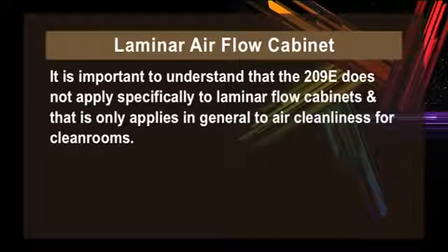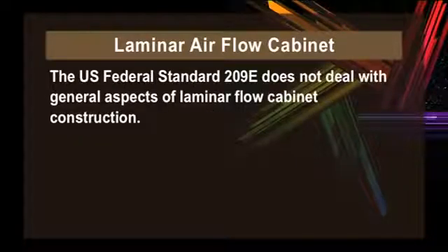It is important to understand that the 209E does not apply specifically to laminar airflow cabinets, and that it only applies in general to air cleanliness for clean rooms. The US Federal Standard 209E does not deal with general aspects of laminar airflow cabinet construction. However, it deals with the most important aspect of cabinet performance, which is the level of product protection provided. In other words, the cleanliness of the air within the working area of the laminar airflow cabinet.